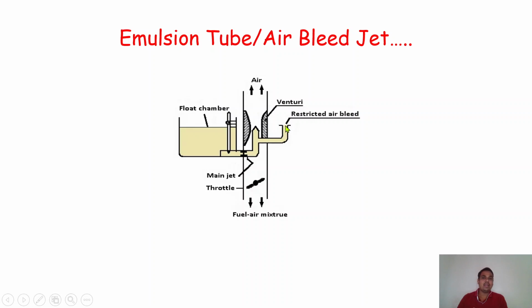Okay, what I am telling, please understand my statement. In this case, what happened? The required or some additional amount of air will come inside this particular carburetor jet, we can say this is about the main jet, that additional amount of air is inserted over here, and because of this additional air there are some changes in the pressure which is created inside this particular main jet of the carburetor.